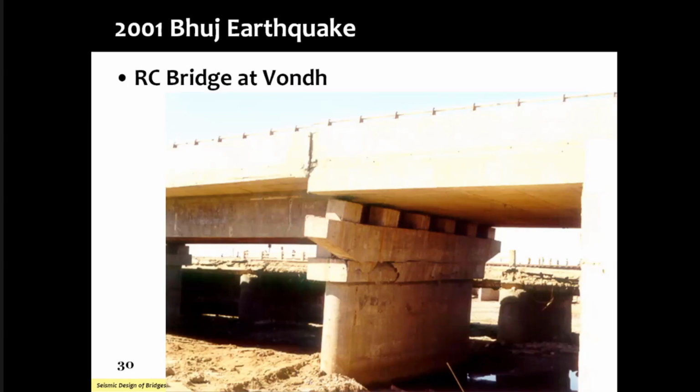So when you talk about seismic design, the first item is called configuration. In this case, bridge structural seismic configuration. And the first requirement I will say for bridges is that the stiffnesses of the vertical elements are all the same, including soil stiffness, and the span lengths are all about the same, and the span weights and masses are also about the same. Only then will you see all spans oscillating nicely back and forth in the transverse direction, and will not have this headache of differential bed block heights.